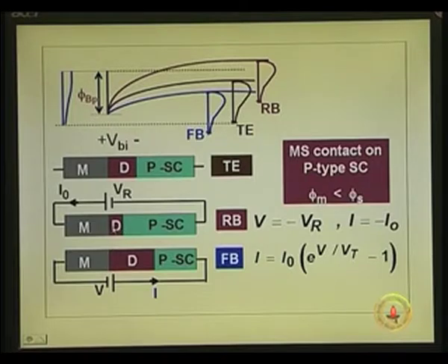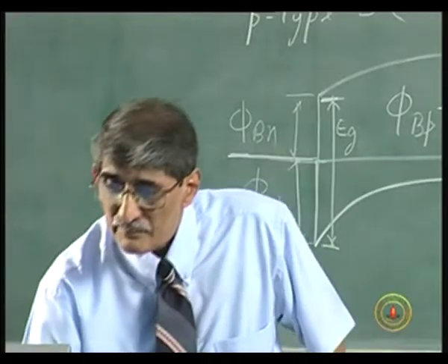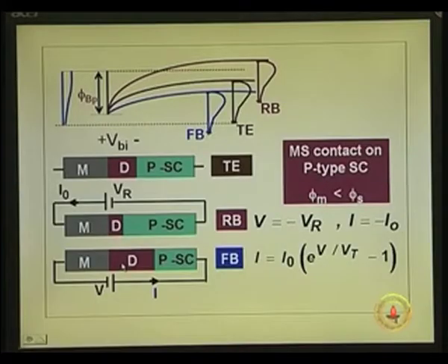So, the depletion layer, D is for depletion layer, it will be wider in the reverse bias case, and in the forward bias case the depletion layer will be narrower. So, when the depletion layer is wider, the barrier height is more. When you forward bias here, the polarity of this voltage is opposite to that. That means the potential you are reducing, that means the depletion layer here will be smaller, okay. Once the depletion layer here is smaller, barrier height will be smaller.